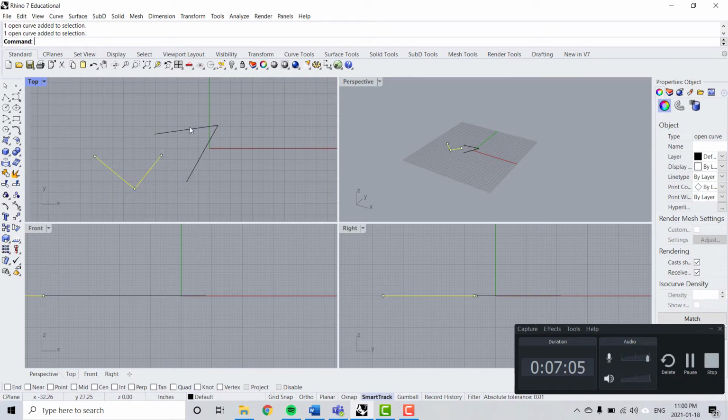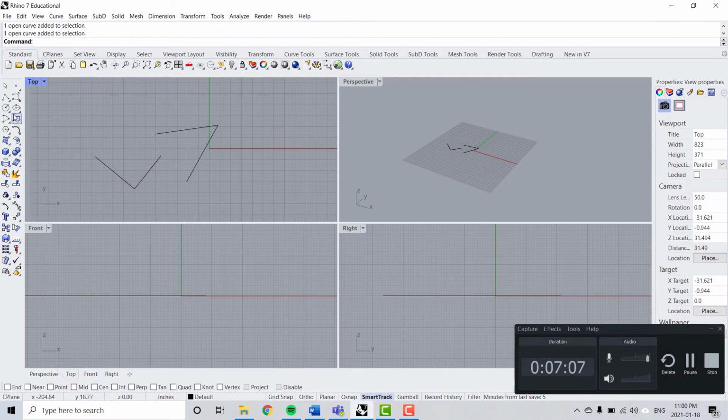And then we have a couple different polylines right here. If you hover over a bunch of these, it's called a ribbon, you'll be able to see the various actions that you can take. So you can hover over here, and if you left click, you can start a control point curve. Right click is a curve through points. Also note that if there's a bottom right arrow, you can click that, and a panel pops out with additional commands that you can choose from.